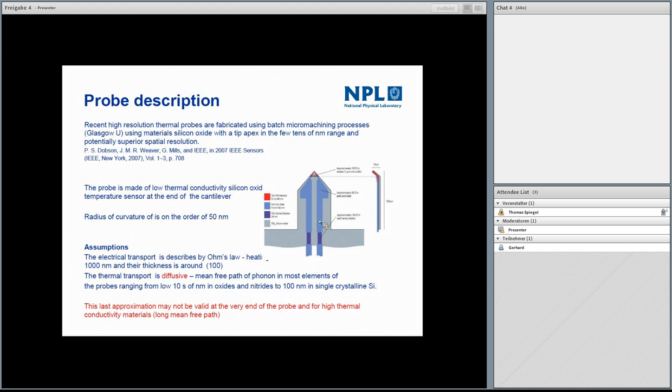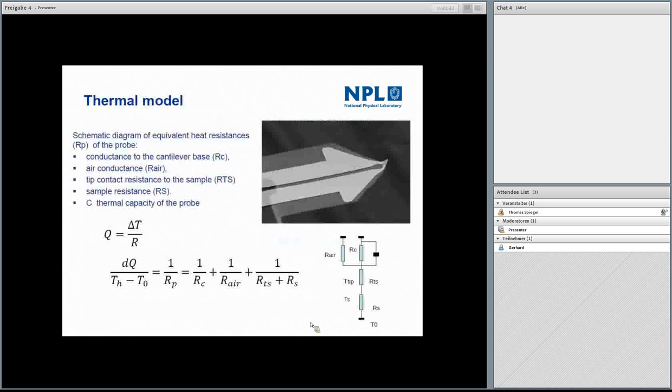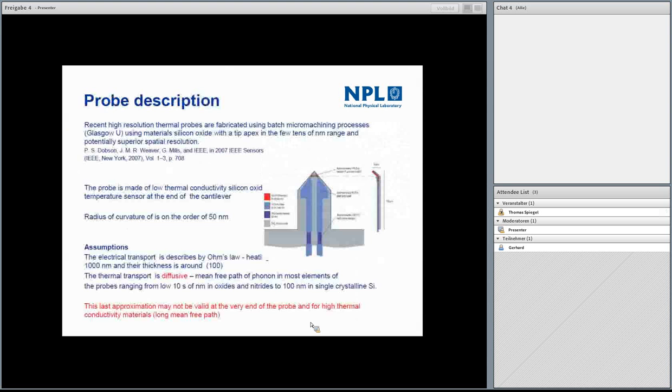So this is a top view, and I'll show you a side view. You can imagine, this is a sort of springboard, a large springboard with an electrode patterned on top, and here the red part is all made of gold, the electrode. Only at the end is it made of palladium. So this is the resistive element, and when you go in contact with the surface and measure the change in resistance through this palladium filament, this will give you a relation with the temperature.